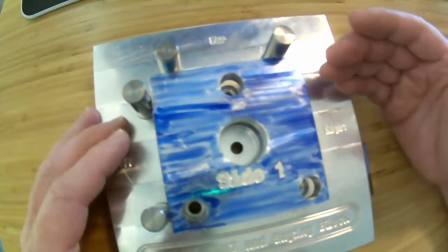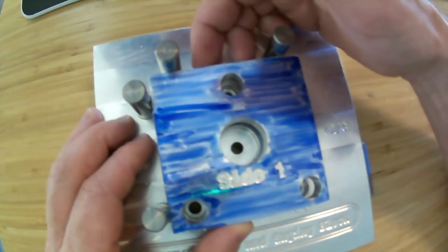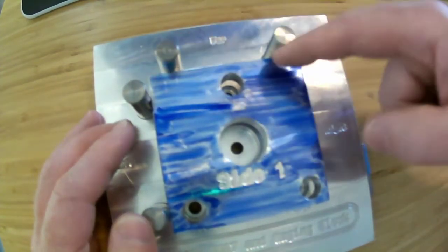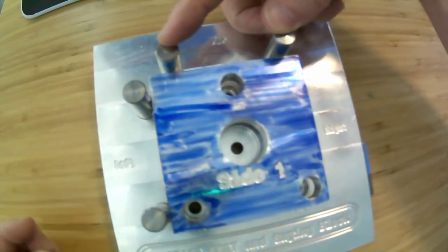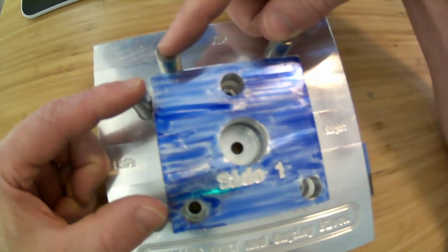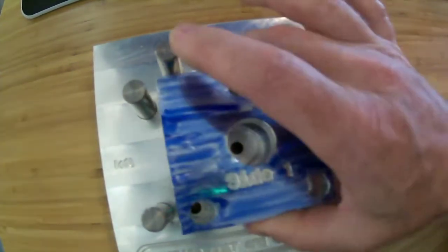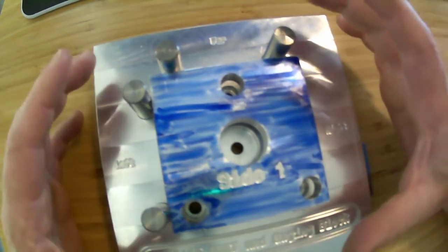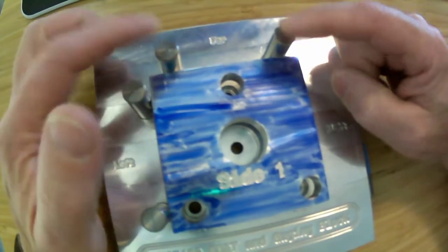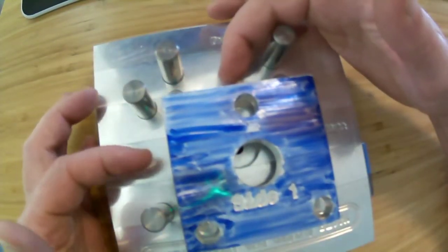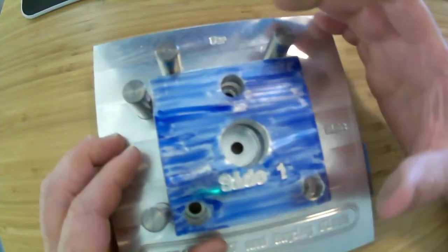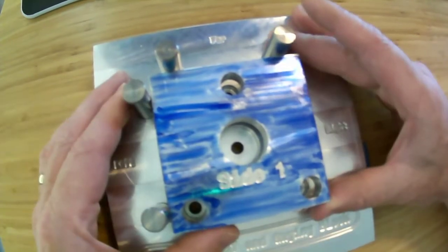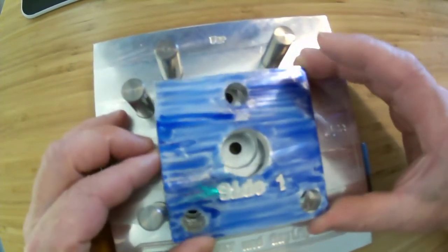And so again, just like the first point, even though I'm locating a plane, the likelihood of me being able to get the plane created by these contact points on these 2 dowels to be exactly perpendicular to these 2 contact points on these 2 dowels and these 3 locating surfaces down here is almost no possibility. And the ability to get this side of the part exactly perpendicular to this side of the part and the bottom side of the part, and to get the surface finish exactly flat, is just not going to happen. So I have what's called over-constrained the part. I have removed this rotational degree of freedom twice.